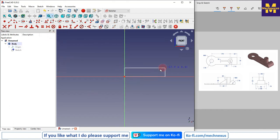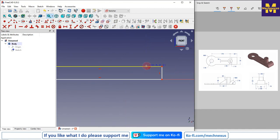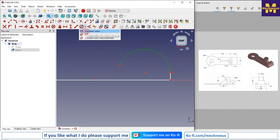So basically I will draw a rectangle like this, and we can see that this is the R25. So I will delete this line, and I will select the 3-point arc, and this is the R25. First I will make the tangent, and then I will give my radius, which is 25.